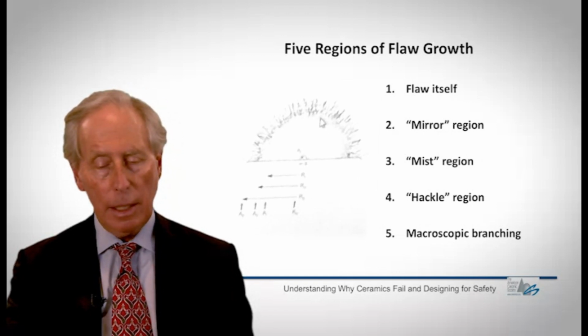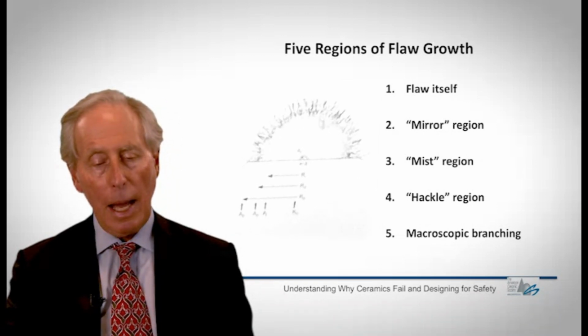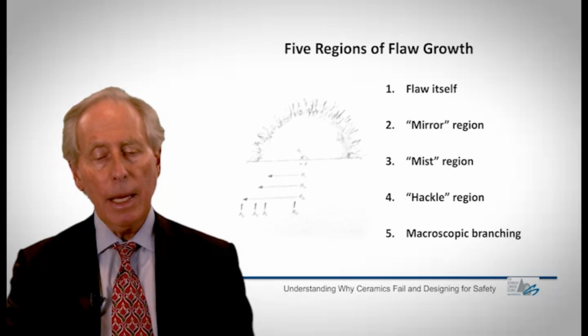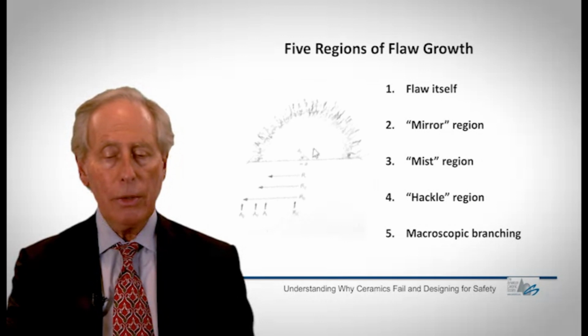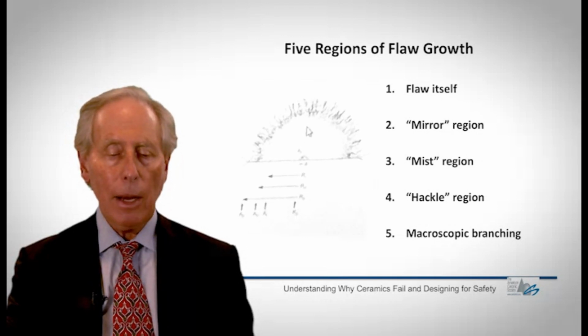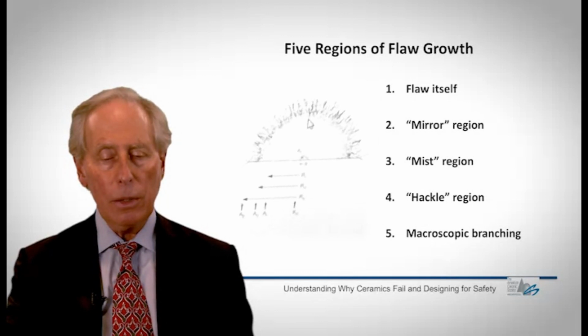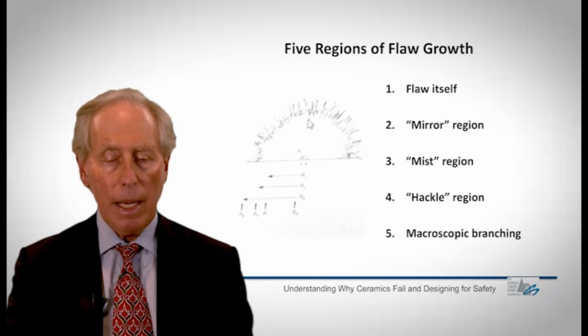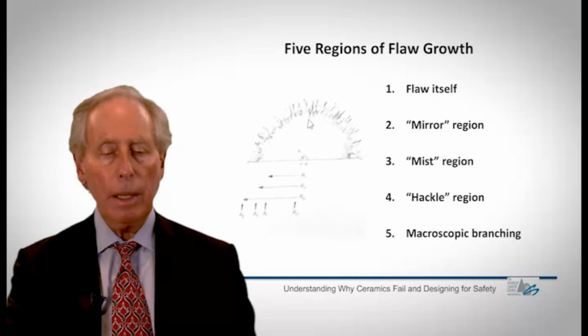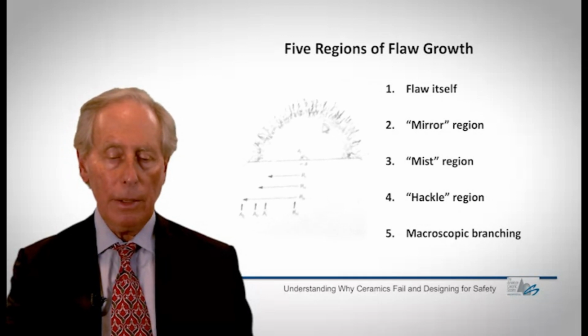This, you can see in here, I think, a little dotted region that you see here. This is where secondary cracks begin to grow, because the crack velocity is such that the energy I'm inputting to the specimen is so large that the main crack itself cannot achieve a higher velocity, so some of that energy goes into the formation of mist, that is secondary cracks that only begin, and so it's a stippled area that you see like here.